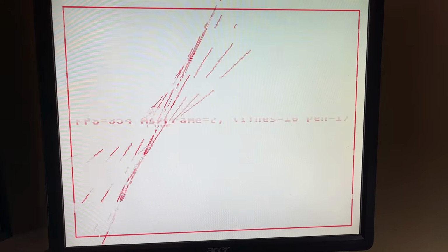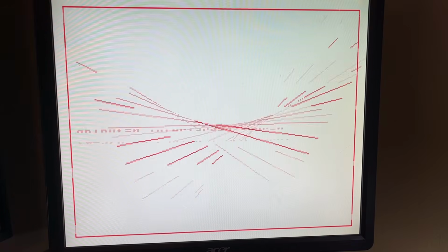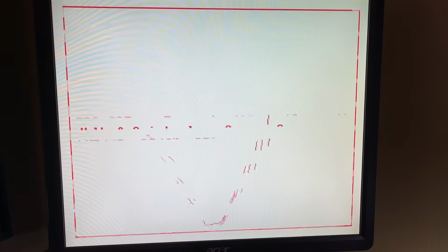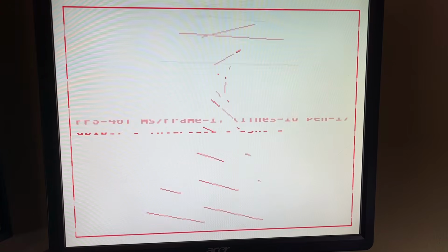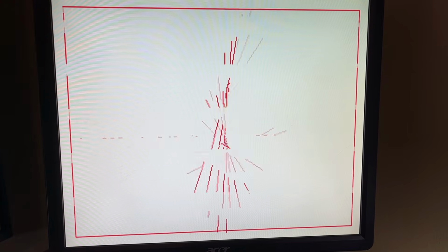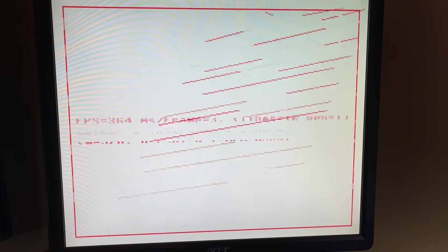So this is 320 by 240 pixels with only 1 bit per pixel. And as you can see, the display is not stable. We're getting what's called tearing in the middle, where we're not able to see all of the graphics. And this is because the frame buffer is being drawn on at the same time that it's being displayed. And when this happens, there's interference. We're actually clearing the frame buffer and then drawing our lines and also some statistics in the middle.